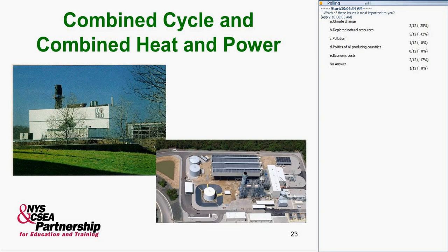Combined cycle heat and power. Here we're looking at efficiencies based on the temperature in and the temperature out. A regular gasoline or diesel motor is not particularly efficient. Best you can get is maybe 25%, 30%. Steam turbines, it's 30 to 35%. If you burn it really hot in a really hot combustion engine like a turbine, you start off by running it really hot. The potential is there to have a really high efficiency if at the end it's really cool.